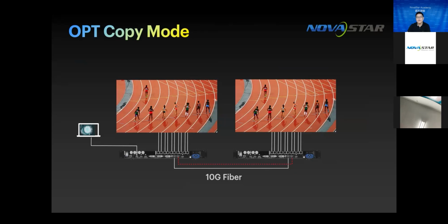For example, if we have 2 side screens on a rental stage showing exactly the same content, we can connect one side screen by Ethernet ports and connect the other by fiber ports. So you won't need a second controller. Here it shows a VX1000 for the second screen, but actually it can be a converter such as CVT 4K. Just one controller is all good for the application.